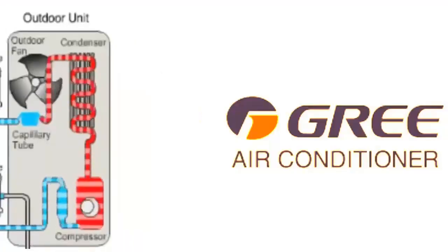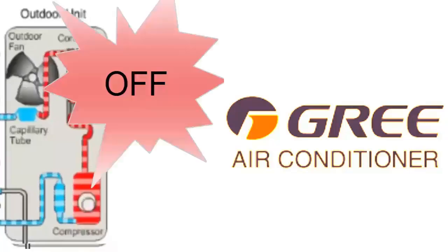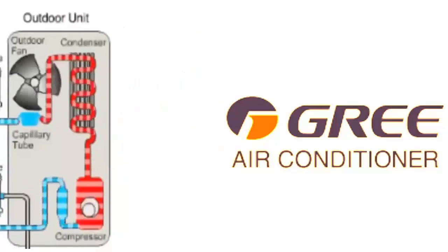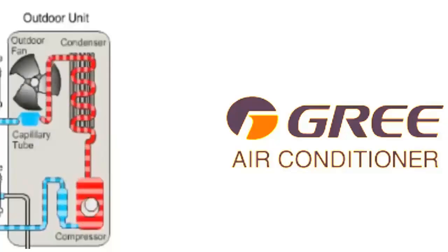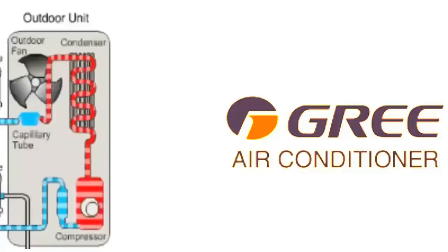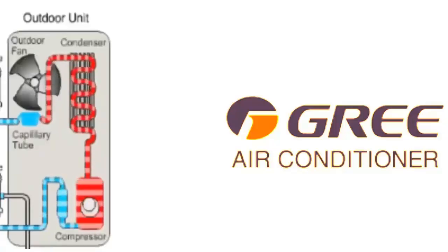When this code is triggered, the compressor and outdoor fan stop to prevent damage, while the indoor fan continues operating. The air conditioning unit will resume normal operation once the evaporator temperature rises above the protection value and the compressor has been stopped for at least 3 minutes.